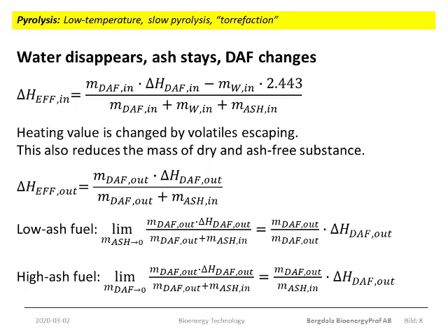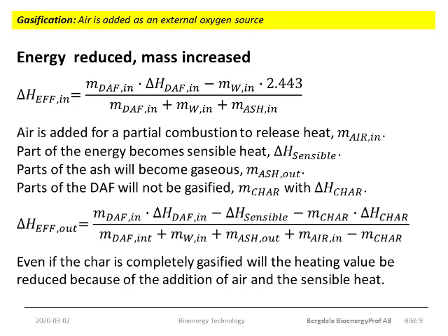So then the total energy losses are kept under control, but they are not eliminated. For low ash fuels such as wood, the heating value will generally increase through torrefaction. But for some high ash fuels, such as rice husk, where the ash content may be in excess of 40% on a dry basis, the result may be the opposite. In gasification processes, the picture is further complicated.